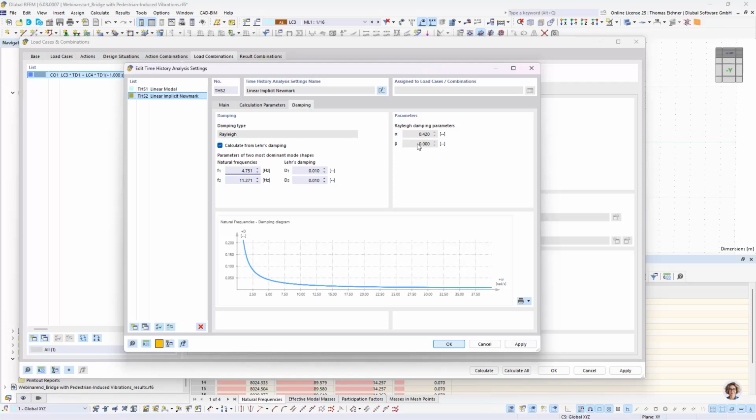damping matrices. And with that said, for the alpha value, what it does is it shapes a curve that starts at infinity. So the asymptote here would be this y-axis, and the asymptote on the x-axis is the x-axis. The beta value also adds an additional asymptote beginning from the zero point, from the origin, and with a slope that is defined right here. So as soon as you enter beta damping, and you would have an infinite frequency, this infinite frequency would have an infinite damping, kind of. And that can lead to problems, at least in non-linear time history.